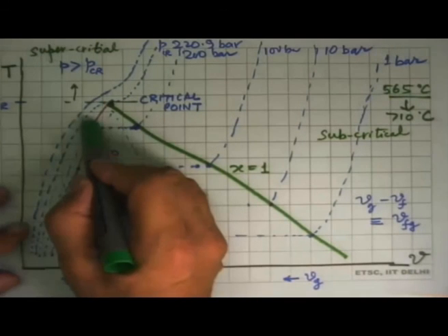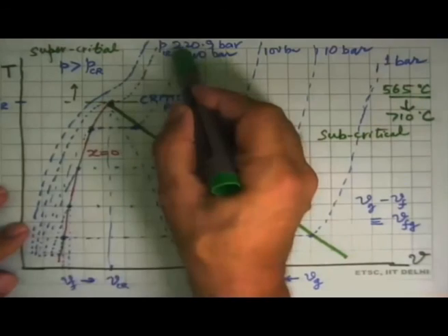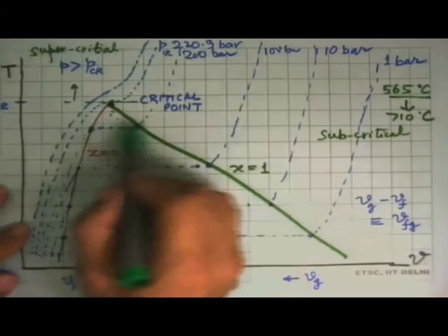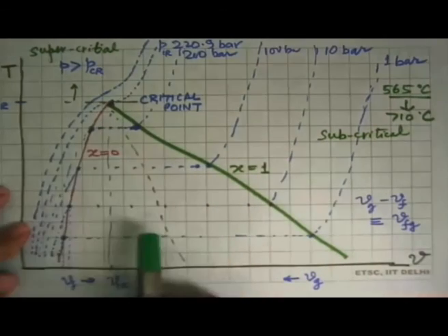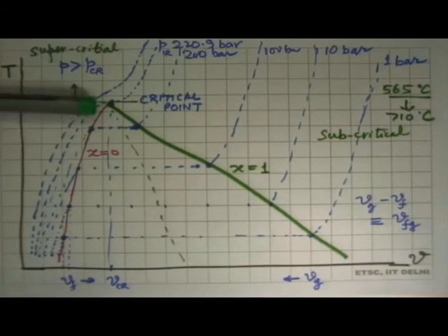This is a saturated liquid. Left of this is a compressed liquid. This side is superheated vapor. In between, we define the dryness fraction. And the top, this is the critical point. So the upper limit of some sort has been set in the properties.